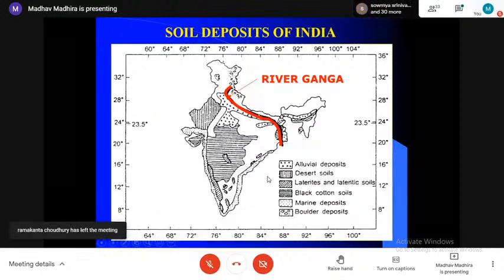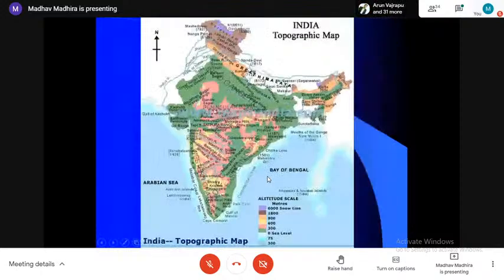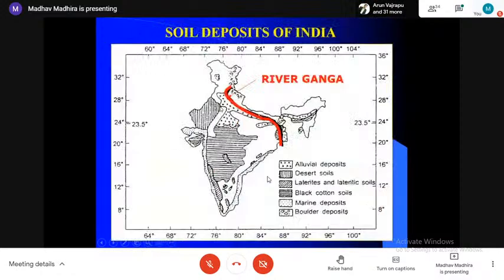This Deccan Plateau, which was originally a basaltic rock, has got decomposed and weathered into what you call black cotton soil. Of course, as a geotechnical engineer, you will say it's an expansive soil or a soil which is subjected to volume changes depending on the season. We have the desert sands here on the west coast, Rajasthan, in western part of India, and southern part of Punjab.